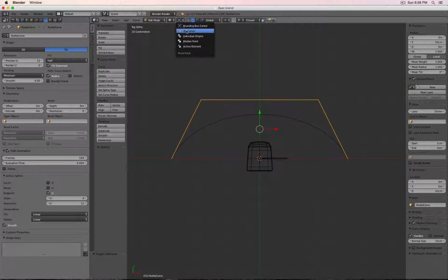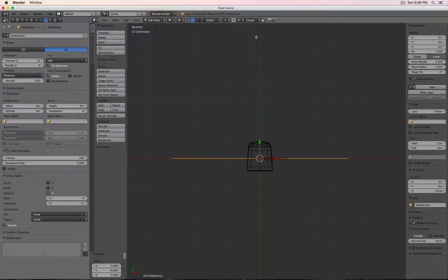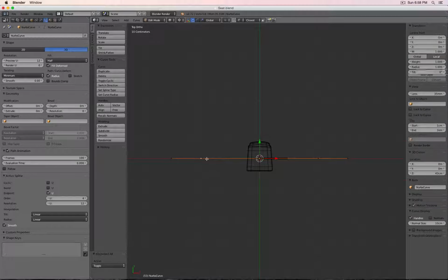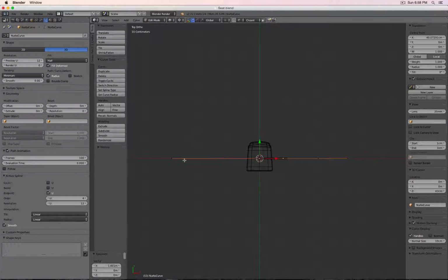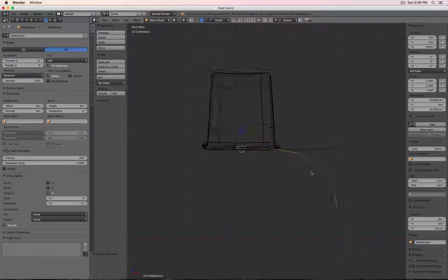I don't really want to see those handles or normals. And I'm going to switch to 3D cursor because now those 2 vertices here, I would like to S, Y, and 0 in my view, scale down. And then this point I move over to there, and this point as X and 0, I scale to the 3D cursor. I move this one to there, move this one over, and this one I move down. So, see there now, I have kind of another NURBS curve.